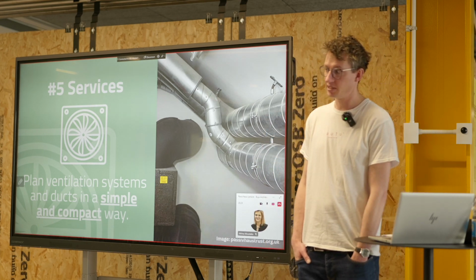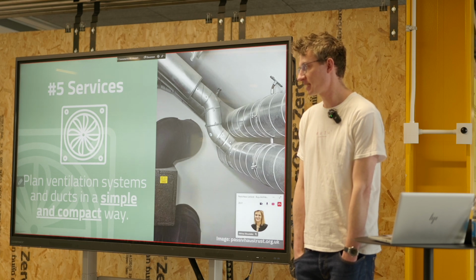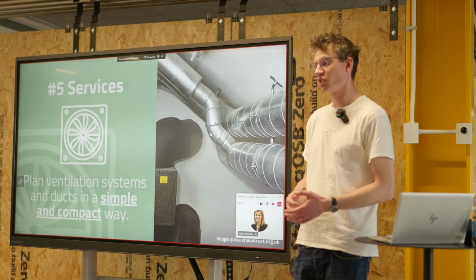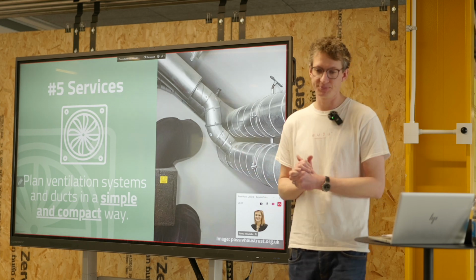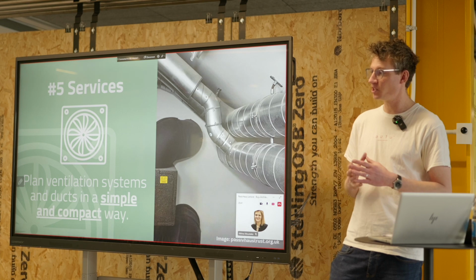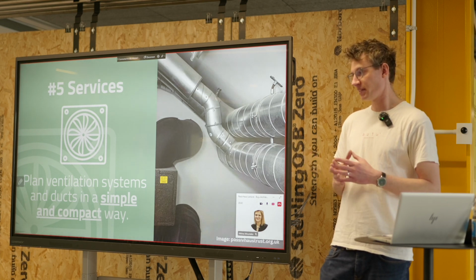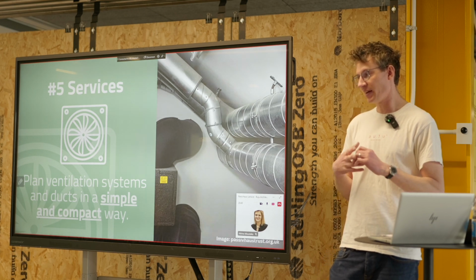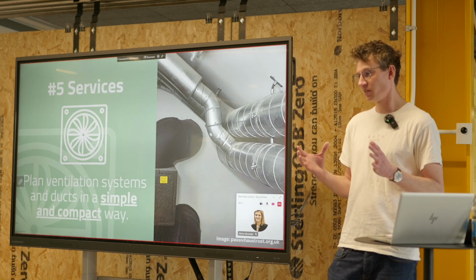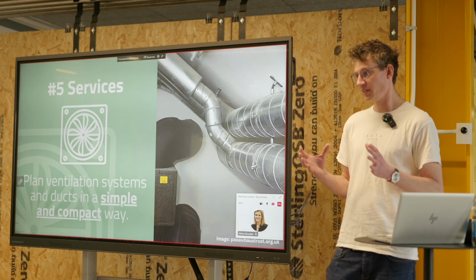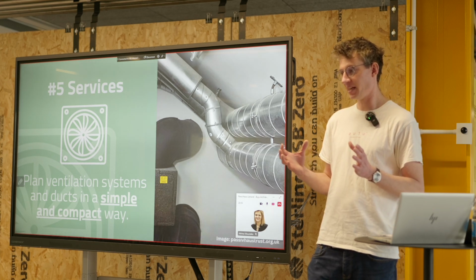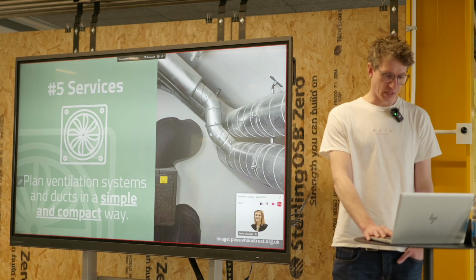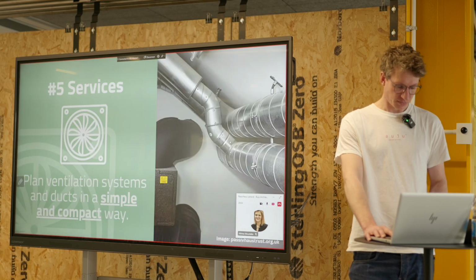Traditionally, or historically, I should say, buildings have been quite leaky. You've been having almost like natural ventilation through drafts or chimneys. As buildings have been getting more and more airtight, they've been introducing things like trickle vents. But it's absolutely fundamental in passive house design that the ventilation is managed not only to achieve good air and fresh air, it's also to avoid things like condensation and create a very healthy environment. So I skipped ahead there, yeah.